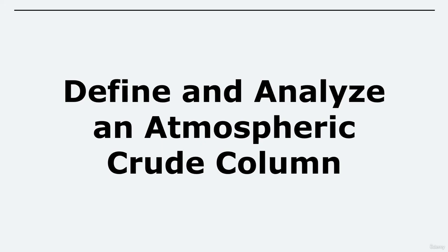Define and analyze an atmospheric crude column. In this video, you will construct, run, analyze, and manipulate an atmospheric crude fractionation column in Aspen HYSYS. You will begin with a HYSYS reflux absorber template and continue by adding side operations and additional specifications to the column model. The final focus will be to utilize cut point specifications on the column model to increase and better define product quality.